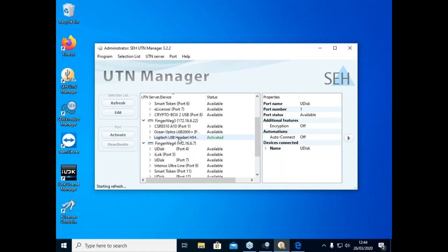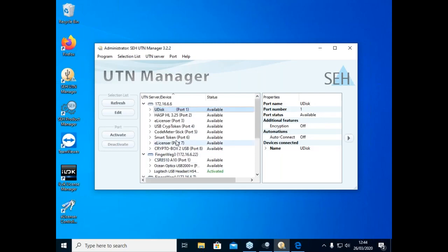This headset is an isochronous device, which is not supported by our old MyUTN 800, 80 and 58. The 2500 and our new Dongleserver Pro support isochronous devices on the USB 3.0 ports, and there you can also have a music card or sound card or a video camera or a microphone or a headset connected, which you can use like it's connected to your desktop itself.